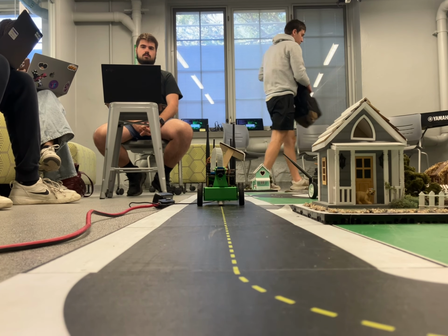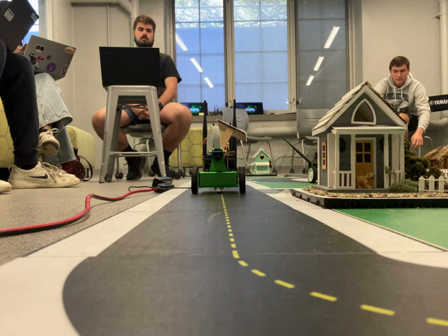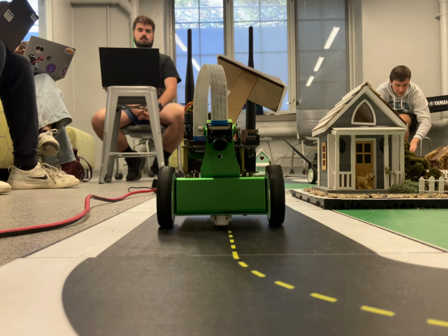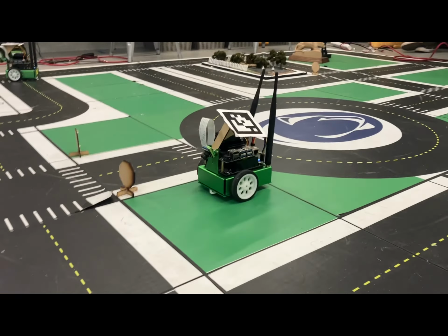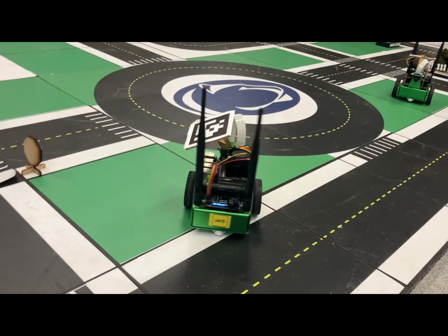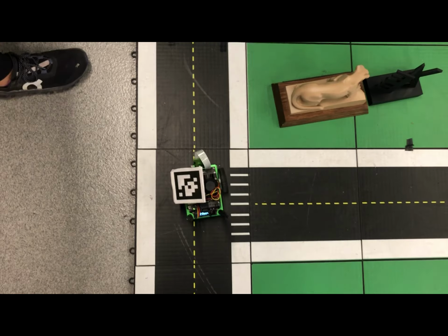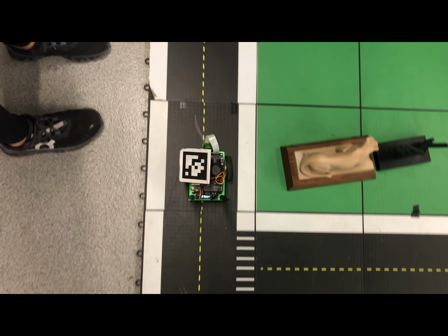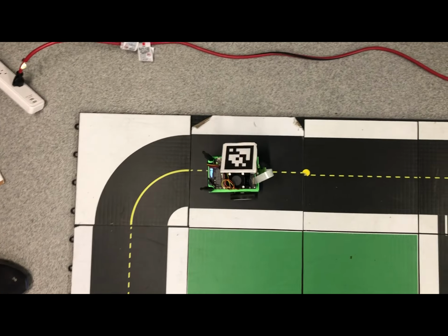In the first laboratory session, our team started by testing the behavior of the differential motor system in the JetBot. We found that inputting equal positive values to each motor resulted in the robot moving in a forward motion in a straight line. Providing a larger value to the left motor would cause the robot to turn right and vice versa. Providing equal magnitude values of opposite sign causes the robot to spin in place. Finally, 2 negative motor values resulted in a backwards motion, with the same logic applying to turning rules for forward motion.